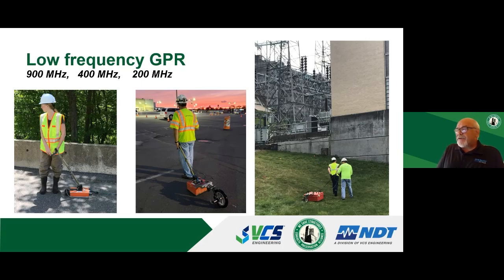But on the left, the 900, this is good for bridge load ratings. This will penetrate through the asphalt wearing surface, the concrete deck, and identify, in this case, a concrete arch and how much soil is on the barrel of the arch. So we'll do a top-down assessment from the road. The technician's got her waders on, and she'll go down in the stream bed and do a bottom-up assessment of the concrete arch, and we'll be able to put the whole picture together for the load rating that's required with the bridge inspections.